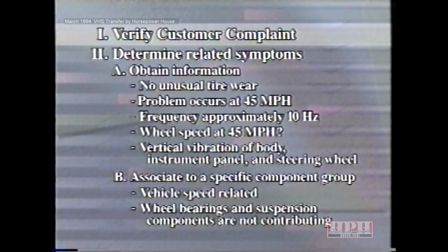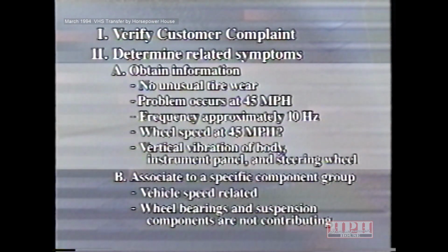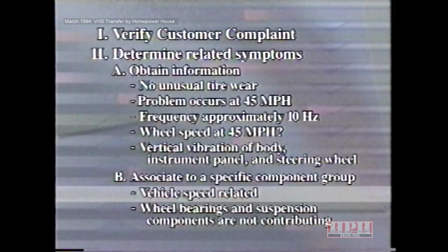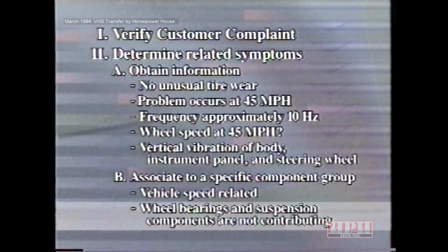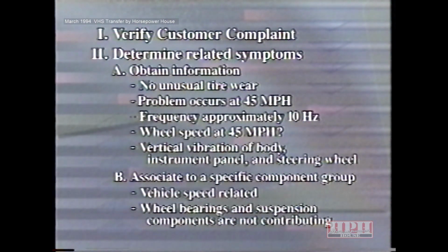We have verified the customer complaint. We know the symptom's characteristics. We also know that the vibration is related to vehicle speed and the wheel bearings and suspension components are not contributing. Because the trouble is vehicle speed related, the only component frequency we will need to calculate is wheel speed.